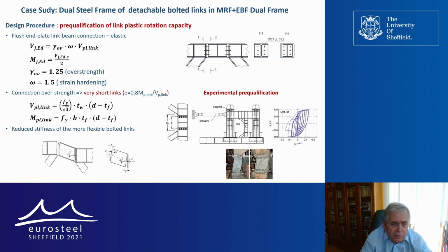We have to take into account in designing the link of the overstrength, potential overstrength of steel, and also the strain hardening effect due to the reversal action.